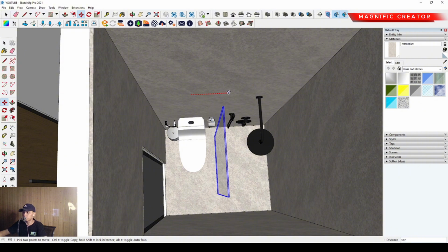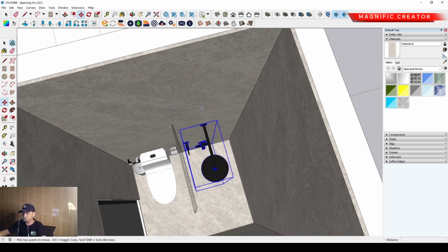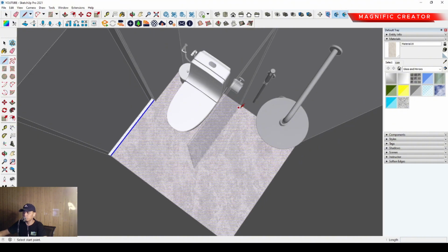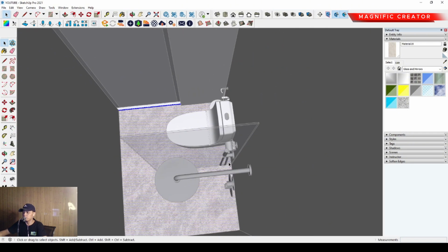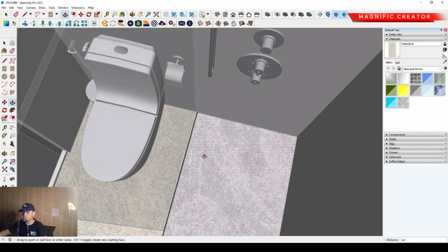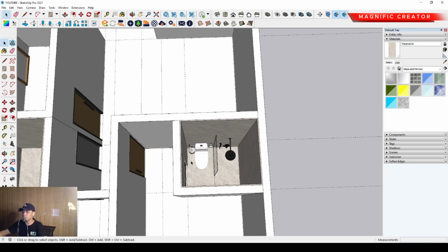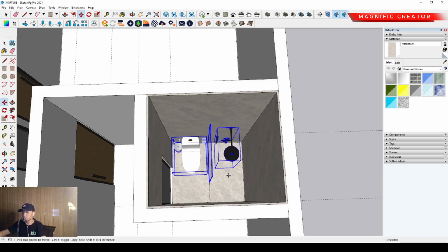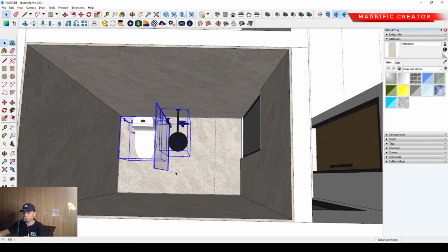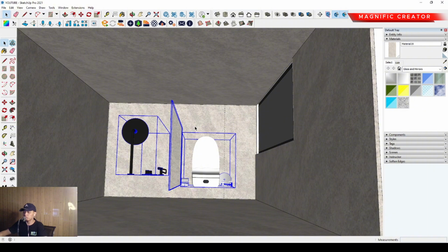Okay, you can see by this. Okay, and after that we can make the difference level between the closet, between the toilet floor and the shower floor anyway. Of course, we have to make the difference level of the floor. Okay, we have to move it down around 20 millimeter. And also for the other bathroom, we have to set it also by selecting this 3D model and duplicate with the control from our keyboard, and set the orientation with the rotate tool.